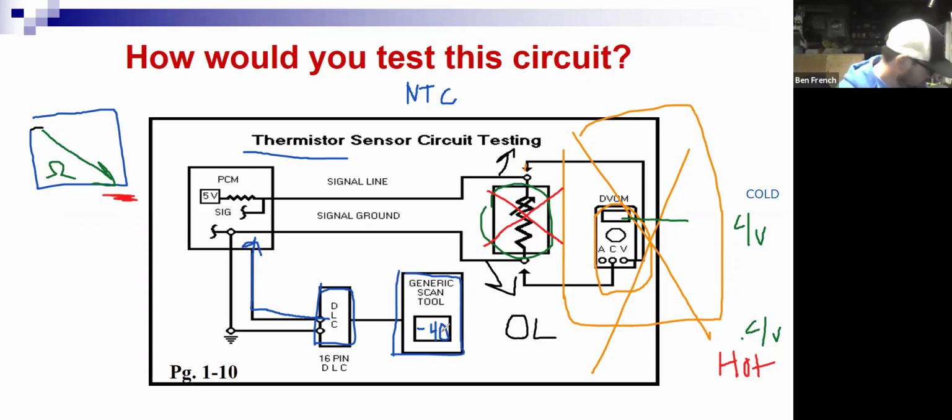Okay, well, that's good. Now, what about low resistance? Well, I could take a little jumper wire here. Got my little red jumper wire right there, and I'm going to hook it up to that sensor connector. So now I'm drawing my little red wire, and now I'm hooking my little red wire up. And so now I've gone to really low resistance. When I hook up my little red jumper wire, now it's going to think, man, I'm smoking hot. Maybe I'm at 260 degrees or 300 degrees, something like that.